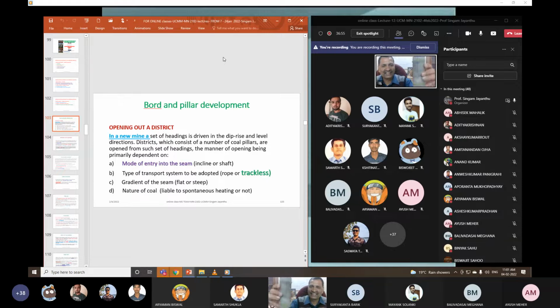You see how this is tested for compressive strength. This is of course with the triaxial test we conducted for some other purpose. These are different rock samples. You can see sandstone samples of different kinds. So what I wanted to tell you is, when it is subjected to compressive load, if it can take some X load, when it is subject to tensile load, it can be broken at almost 1/10 of that load itself.